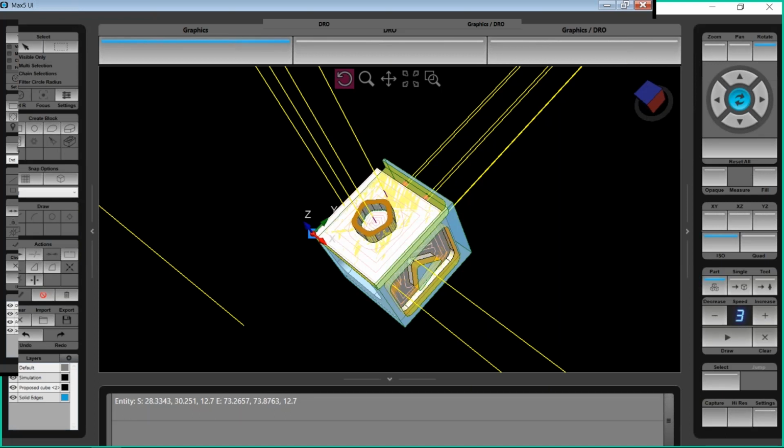If you do a lot of NC or G code programming, I recommend leaving that set to no. It can cause unexpected issues. You will not be able to disable tool center point management. You will not be able to disable 5-axis linearization with that workpiece transform enabled. So if you're running G code and you want to cancel tool center point management, you can put an M129 code in your program, but it's going to be ignored because the control forces tool center point management on whenever a transform plane is active. And what that enable workpiece transform does is activate that transform plane at all times. Okay?